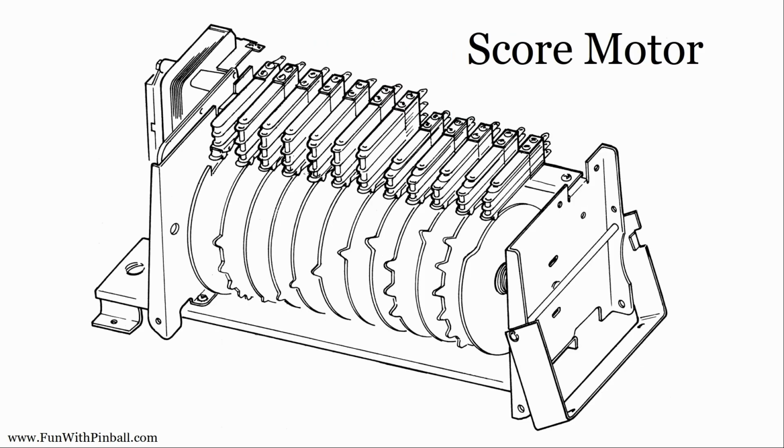Let's talk briefly about a score motor. So a score motor, this is a picture of a Bally score motor. Williams used a very similar design. These cams rotate towards you in this drawing. These little nibs will roll by and bounce the switch stacks that are mounted to the top of the score motor, right? But notice that the little nibs are all in slightly different positions. So these are firing a little bit like the pistons in an engine in a very specific sequence and a very specific timing relative to each other.